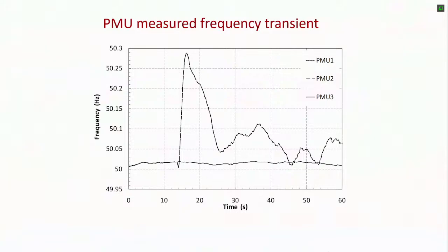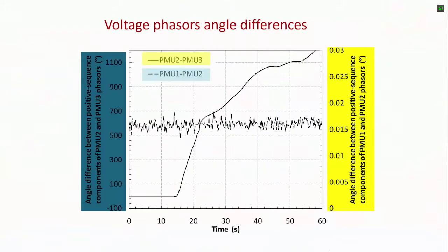And this was a good thing for us to see, because this also corresponds to the measurement of the speed of the turbine in the power station. So we can compare the accuracy of the PMU with respect to the actual measurement of the speed in the substation. Obviously, the speed is increasing, but you see that the gas turbine is able to control the frequency. Obviously, it is not exactly the same frequency of the network. And these are the measurements of the angles.